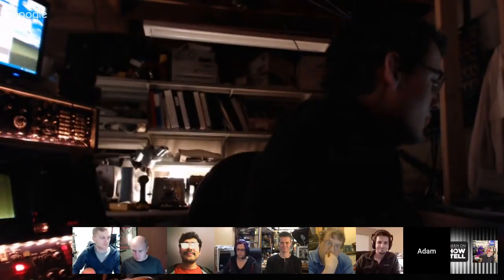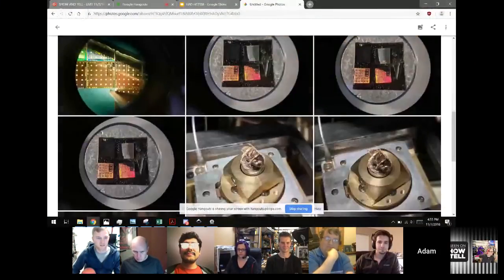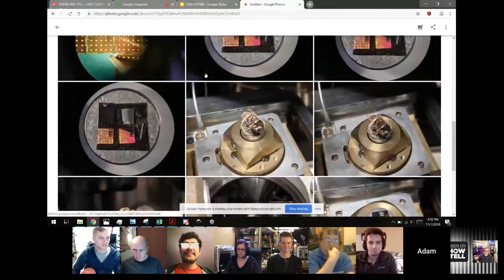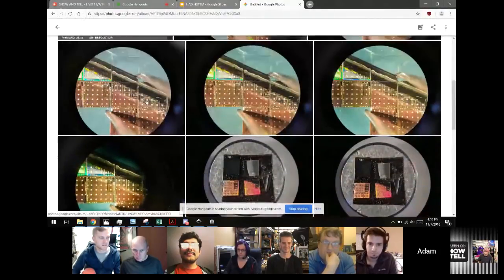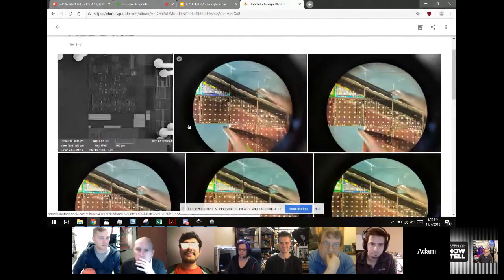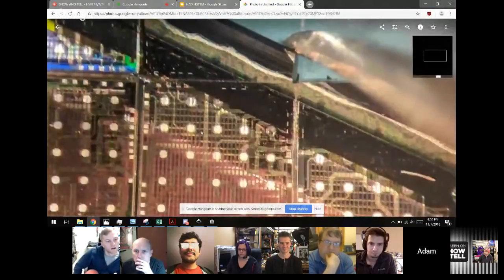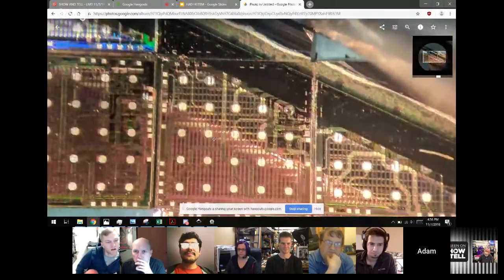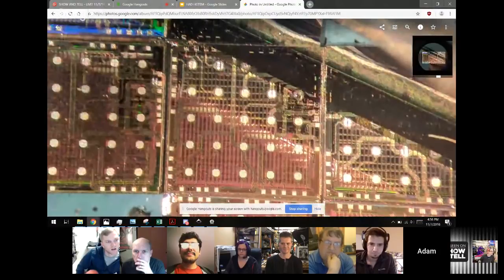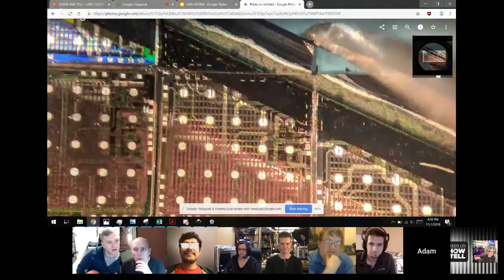I was also at SuperCon this weekend, and Scotty from Stranger Parts gave me some really cool, random stuff for the market. I got this large pile of reject direct on board chips. What was interesting is that if you look at these, the edge starts to fade out, as the manufacturing process goes from here to here. So you've got this in-between layer where there's no passivation present, which means there's no glass layer on top.